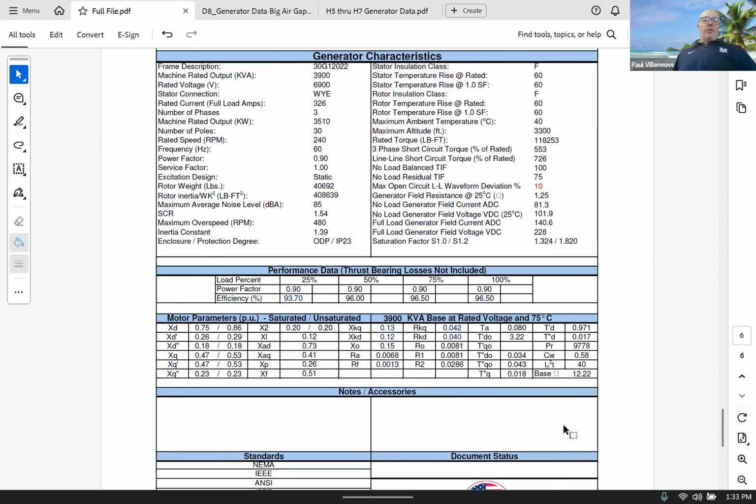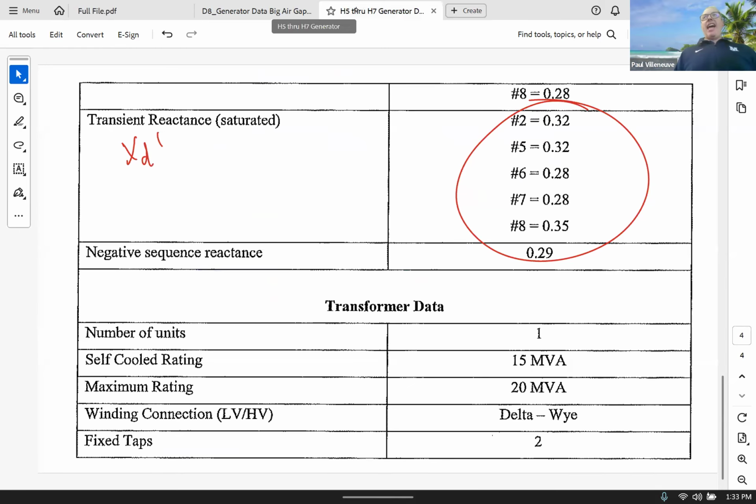Well, the only reason why it would have been very difficult to use that value is that over here you don't actually have the steady state values, right? So your per unit diagram would have been very confusing. Is it steady state or is it transient? So maybe if you had marked up saying these are transient and these are steady state, the diagram would have had two different representations. And if you would have added that note saying I use the two different ones, you probably would have been fine. But when you're doing these diagrams, they have to be based at the same time frame, if you will.